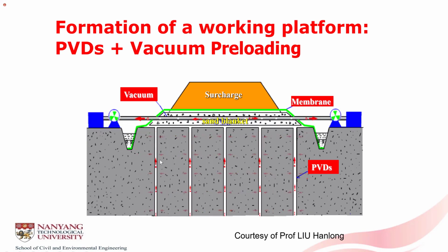You use a suction pump to apply a suction into the marine clay, so then you reduce the pore pressure and increase the effective stress, to consolidate the soft clay. The difference between a fill surcharge and vacuum consolidation is that vacuum creates an inward movement, so you will not have stability problems.